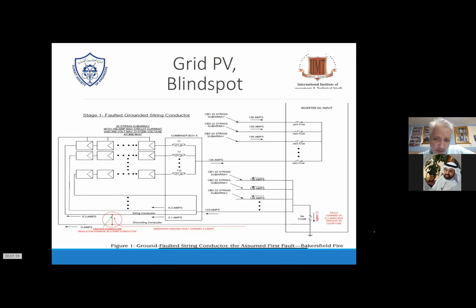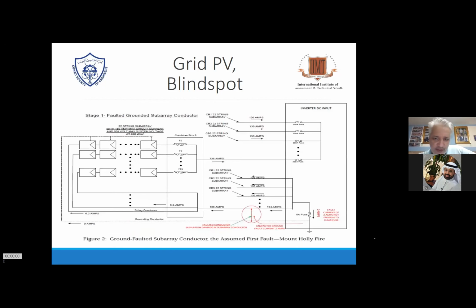So it is quite dangerous when you earth. I mean, these systems would not be done like that in Germany, and at that time, that's also some years ago, we also did not have so many problematic issues with that, because like I said, we don't earth one string. So we have 2 floating strings, plus and minus, and it's also easier to measure the startup voltage. Once, like here, you perfectly ground one pole, you can have these effects.